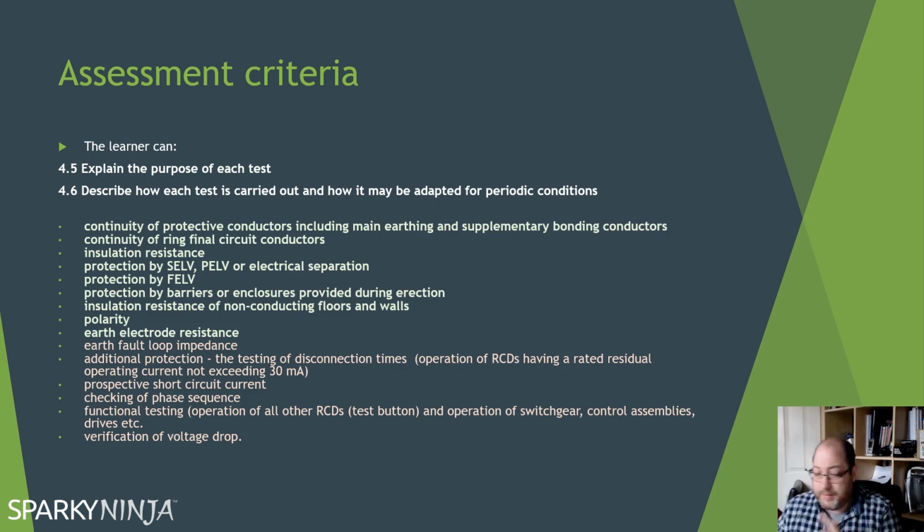Functional testing, I see a lot of people go, yeah, that's just a tick thing. Once you've done your RCD tests, the last thing is you go and you trip it and that's done. That's true, the RCD test does require functionality verification. If you look at the schedule of test results, that is all that it really now asks you to record, but you need to know that the functional test is not just that. You need to verify the functionality of your overcurrent protective devices, your MCBs. You must verify the functionality of any dimmer switches, control switches, thermostats, anything that functions. You need to verify its function.